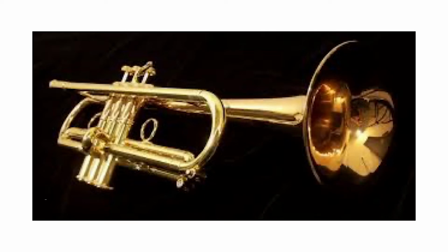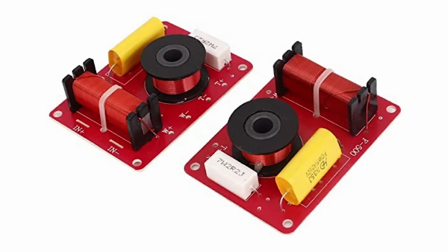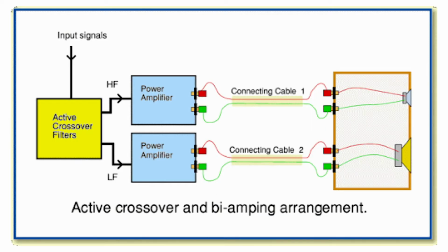A speaker box with a woofer and a horn or a tweeter is referred to as a two-way cabinet or a two-way box. In most basic and very common PA speakers, that implies a passive crossover network inside the speaker cabinet, as from the earlier episode. In more heavy-duty professional speaker enclosures, each part of the speaker cabinet is fed directly by an amplifier with an active electronic crossover feeding the amplifier's inputs. This type of configuration is referred to as a bi-amplified system.